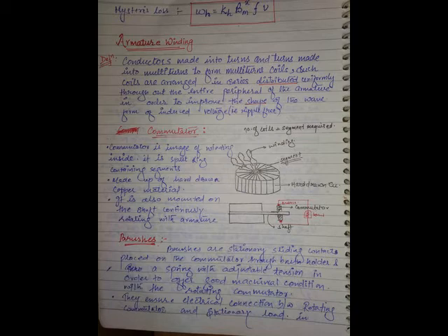Let us think like this. When one conductor passes by a north pole, first voltage is induced. All the 50 turns are the same. Next, the south pole comes. It will take some time, and actually this is the voltage. So we'll take it like this. This is the voltage rectified after the brushes from a 50 turn or 100 turn coil.